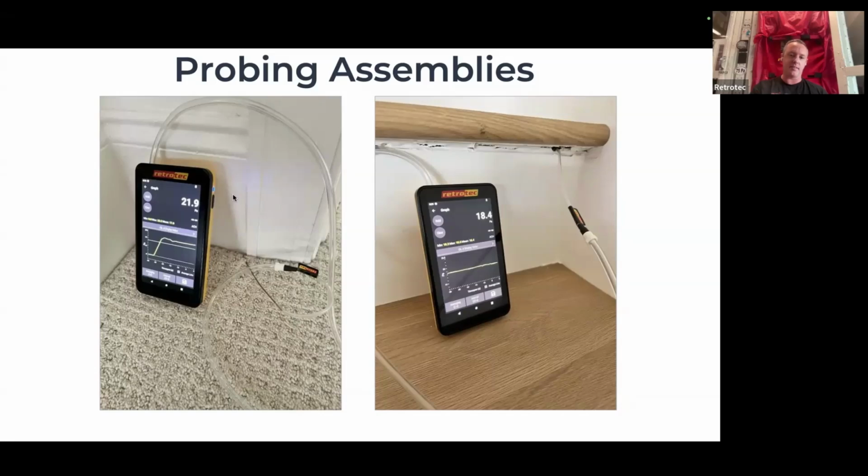And what we found is that this wall actually goes up, and as it extends, it turns into an attic knee wall that was open to the attic. So as we were running the blower door to depressurize the house, it was just pulling attic air into that wall. And that happens in the summer too. When we're cooling and it's hot outside, we get that reverse stack effect. That's just going to pull air in from the top and then lose it out from the bottom. Air travels the path of least resistance, and there's not much resistance there at all, with just the top of a wall open to an attic. So we ended up blocking that off and foaming it to get it good and sealed.